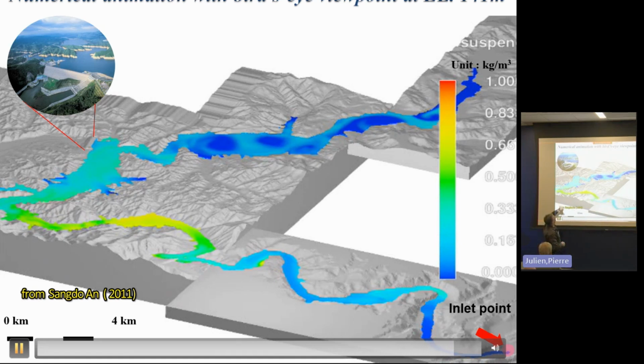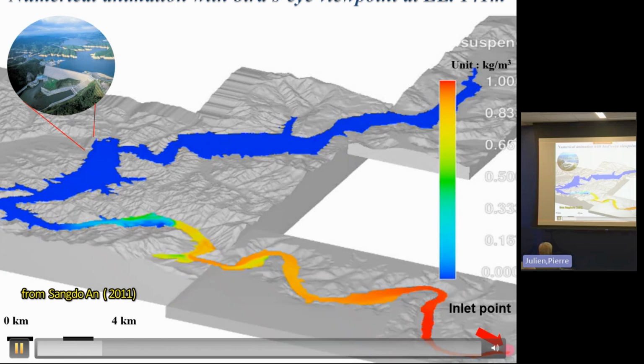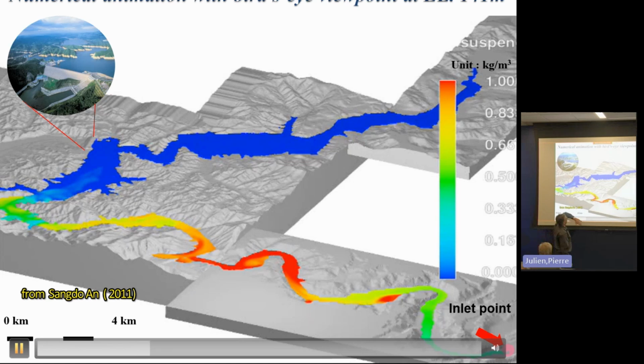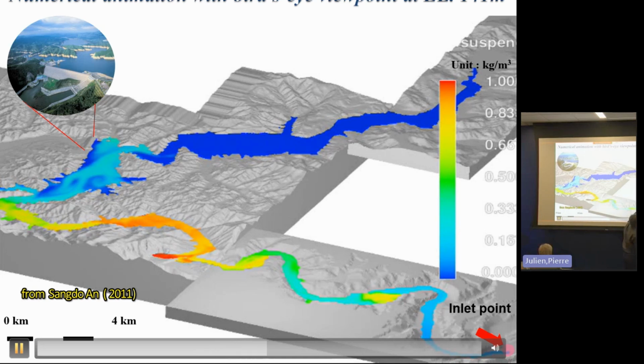Our intake, the dam is up there, and you can see where the intake is, that is the elevation of the intake. Oh, we get it twice for the same price, so that's good. So the intake is up there, and then at that elevation of that simulation here, you can see concentrations up to 1,000 milligram per liter, 500 is in the green, and 150 in the light blue and so forth. So you get a range of concentration through this system.